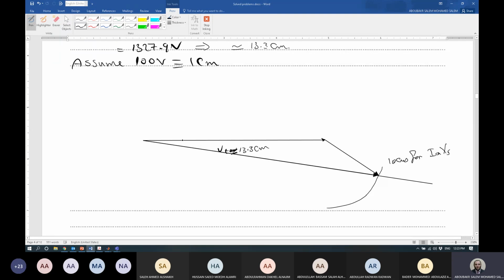You already know the angle. So you can measure 15 degrees from the V terminal and draw a line. This line will intersect with this curve at a point. This point of intersection is the vector length of EF. So this is the way, guys, how we could obtain EF graphically. Okay, is everything clear? Clear.